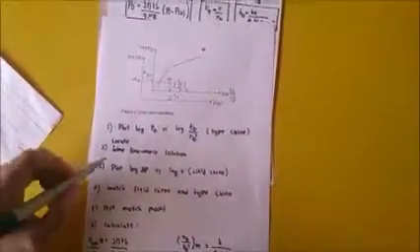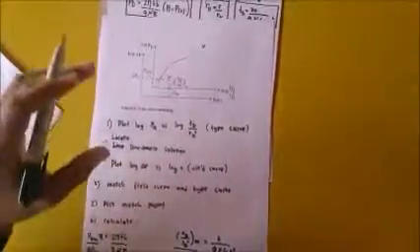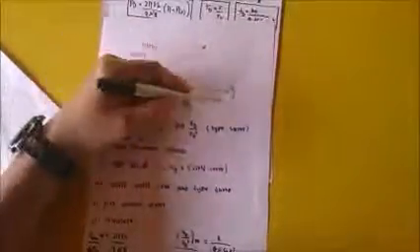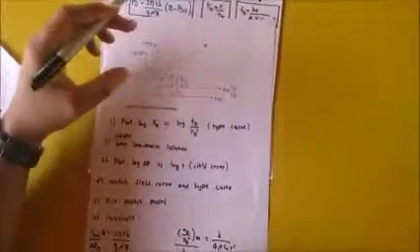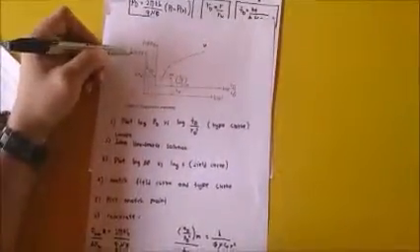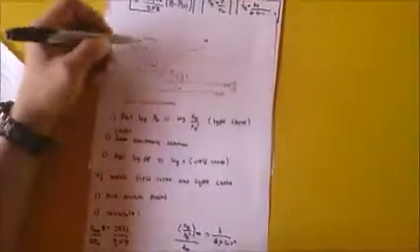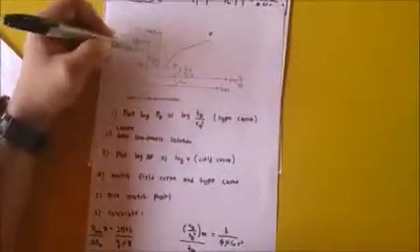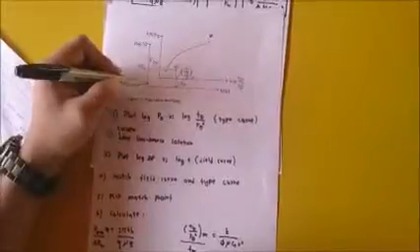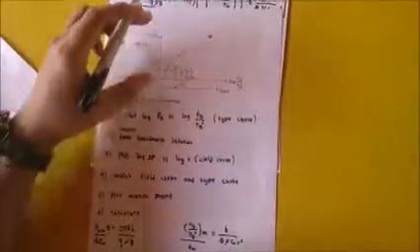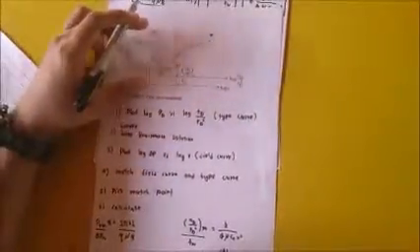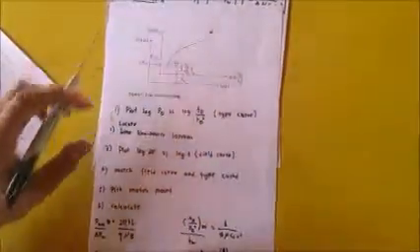The third step is we put this plot on the log delta P versus delta T graph. This graph is called the master curve, and it is provided. So we put this graph on this master curve.